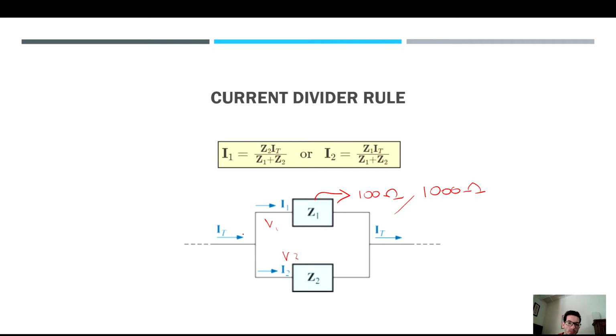So for a DC circuit we applied the Kirchhoff law, but in an AC circuit, depending on the element, it's not as simple because there's some phase shift. Now what we're doing is adding and subtracting waves, which, if they have different phase, is going to be pretty tough to add and subtract. We saw that before. If you want to compute this current, please go ahead and look at the current for parallel circuits. You have to use the square root and the magnitude of the current to know your real component and your imaginary component. So if you want to find the current through each leg or branch, you simply have to find it using the current divider rule.